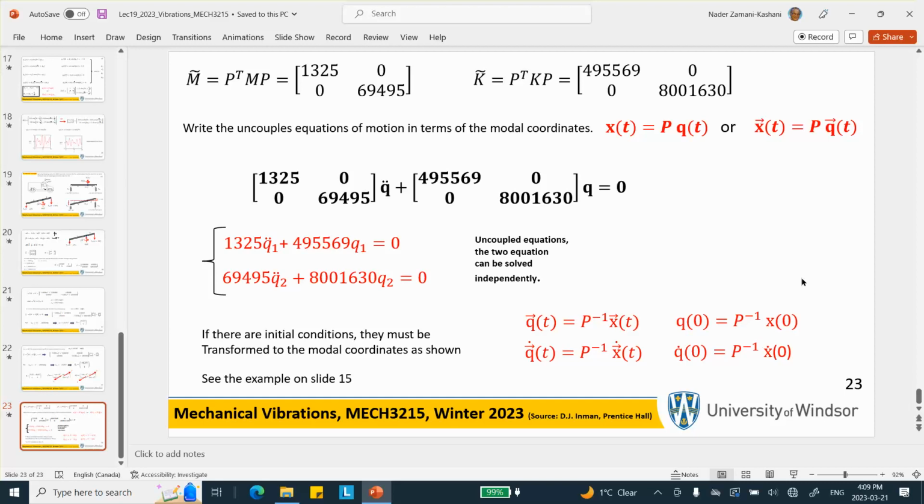When you idealize the problem with finite element or lump it according to what we have done here, you reduce that to a finite number of frequencies. Not all of them necessarily are going to contribute substantially to a particular behavior of the car that you may be interested in. So of all these frequencies, maybe 10 of them or 20 of them, whatever, are the ones that are going to substantially contribute to the system.